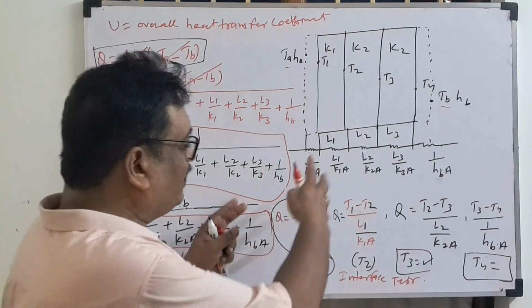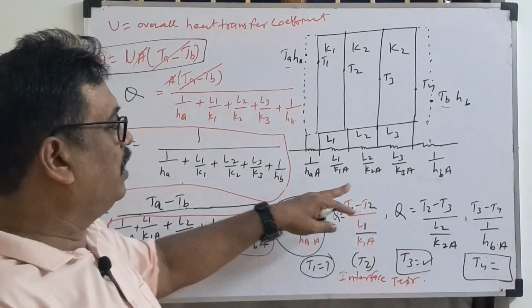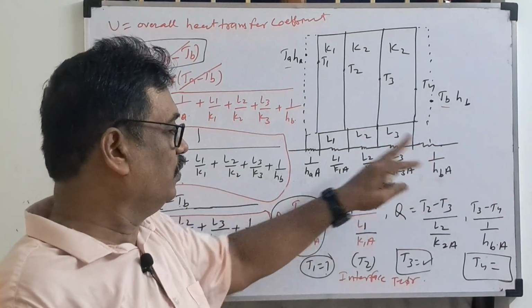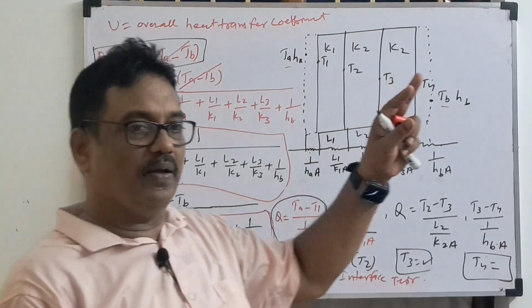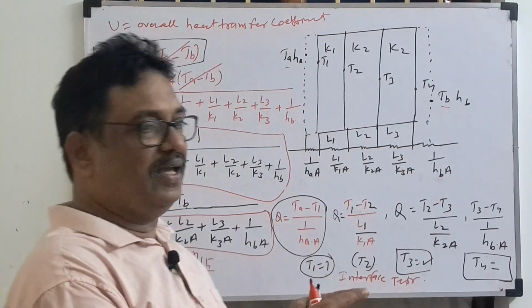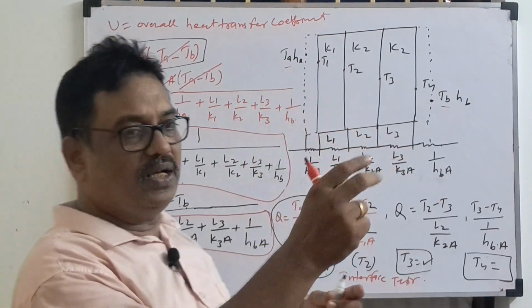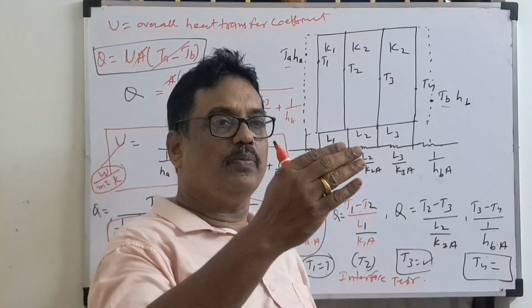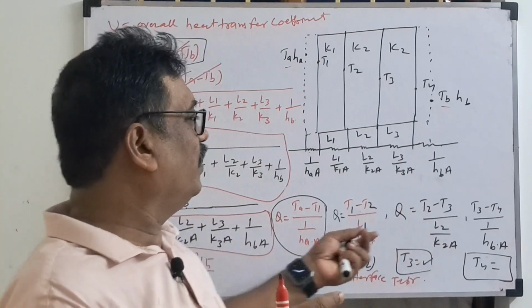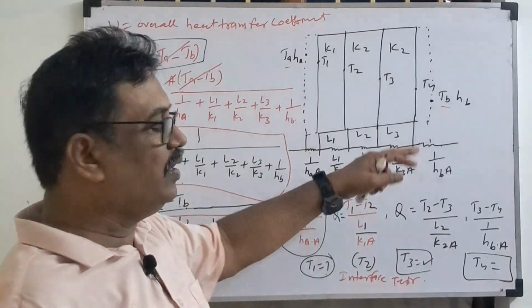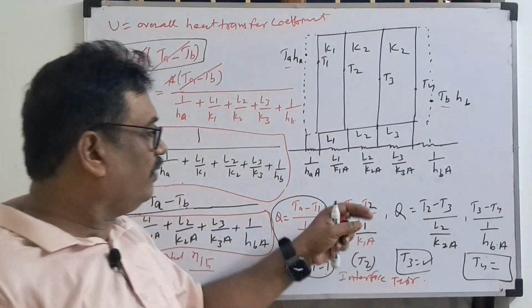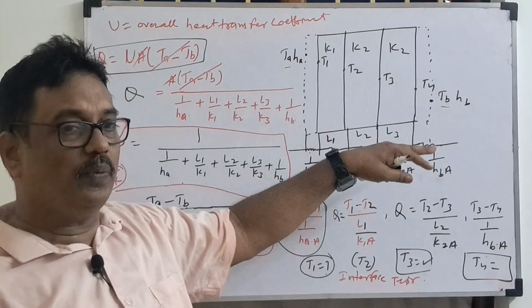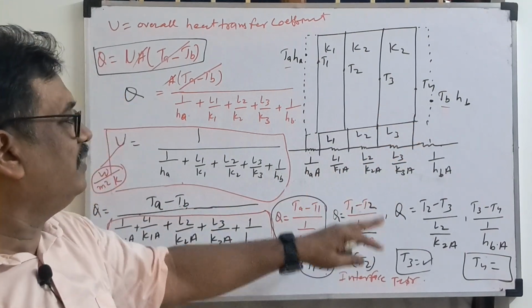Again for the cylinder, we will analyze the formula like this. How to write the formula, that also I will tell you. From the conduction itself, we will go to the cylinder where the area will be 2 pi RL. Substitute that area, you will get the thermal resistance. Again we will go to the sphere, where the area A is 4 pi r square. That way only we can find the formula. We will find the thermal resistance for everyone, correlate this and get it.